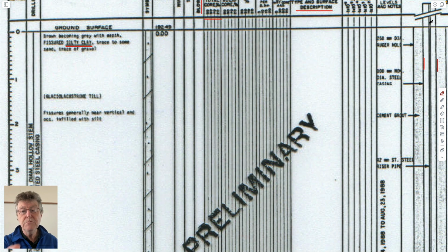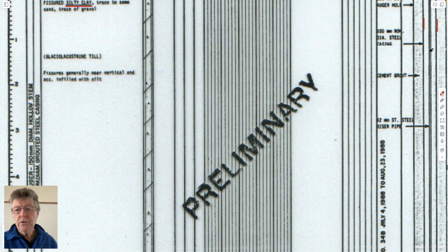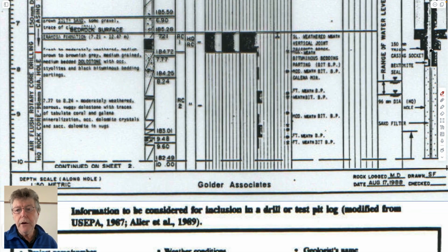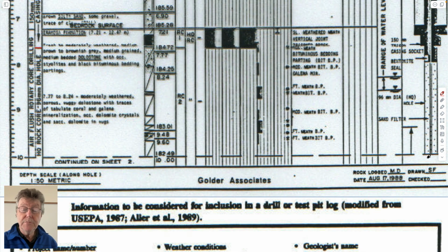This tube down the middle, probably a 1-inch diameter piece of the plumbing that you have in your house, goes down all the way into the aquifer to some depth. We'll talk about what they look like at depth, being backfilled around that with sand to stop the borehole collapsing, and then being grouted in place to seal it. And so you can take water level measurements from this, and you can also conduct pump tests.